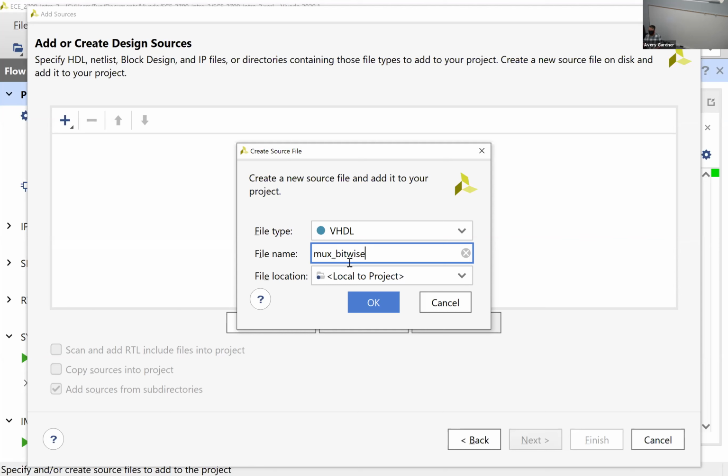Something to be careful of in VHDL and most engineering software is they tend to not like spaces in your file or folder names. If the place that you save your files to or your file names have spaces in them in Vivado, they will not work. They will crash Vivado, and sometimes it will crash Vivado so bad you have to reinstall it. Engineering software in general has issues because they're not designed for mass distribution.